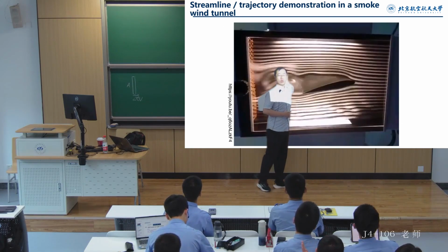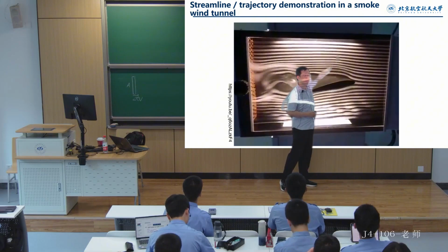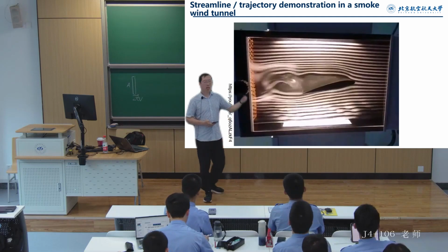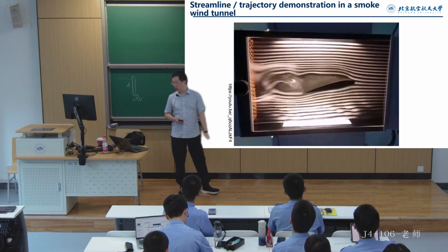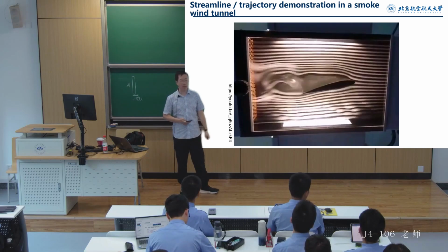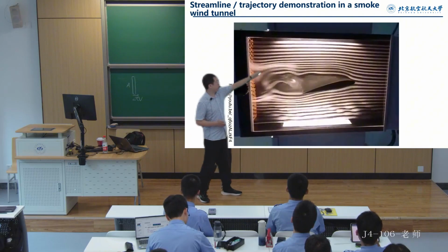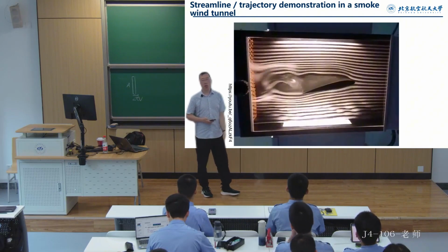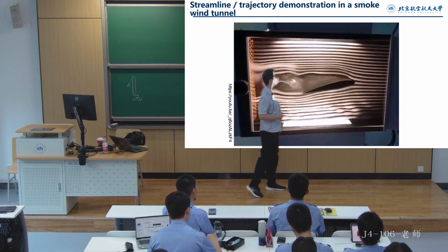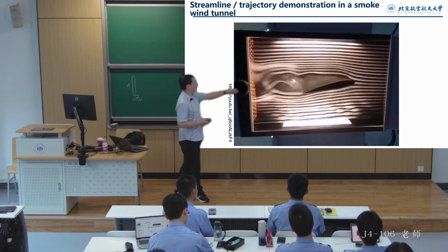steady flow, right? It changes over time, so we mainly focus on these outer parts. Now, these outer parts are actually a steady flow. By using the smoke and observing its changes, we can understand the conditions within the entire flow field. So the entire trajectory that the smoke follows, if it is a steady flow, is called a streamline. For a steady flow, the streamline and the path line are the same. Through this analysis, we can directly obtain the pressure and velocity distribution within the entire flow field from the streamline and path line.